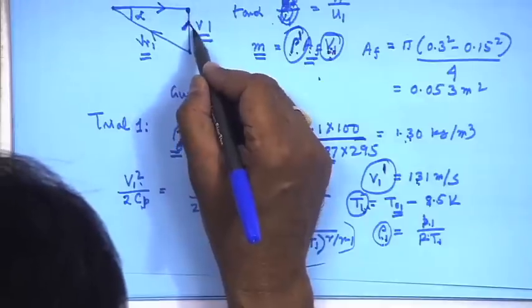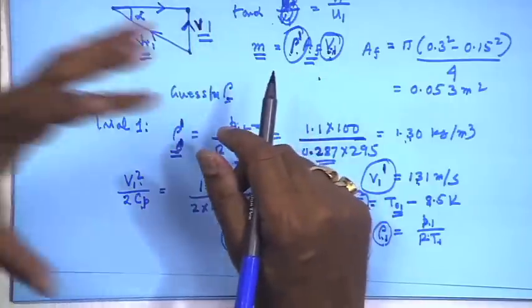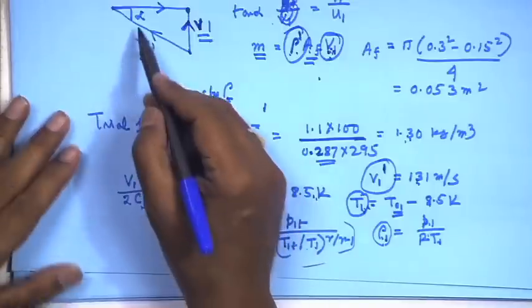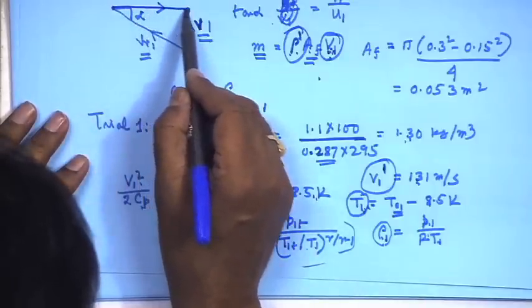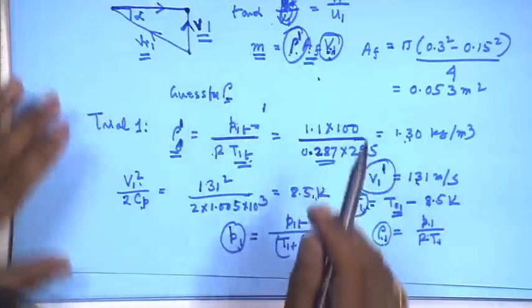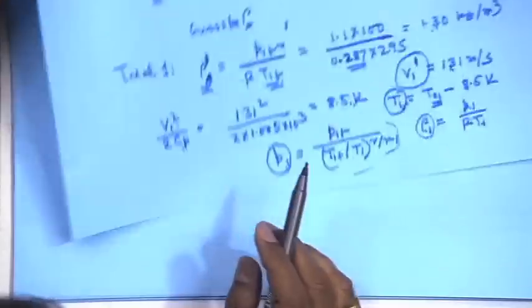When we get the V1, which is constant, the axial velocity of flow throughout the impeller passage is the same. That means it is the same at the root and tip. Then when we use the peripheral speed at the root, we will get the angle of the vane at the root, and at the tip we will get the angle at the tip.